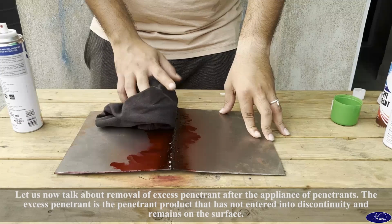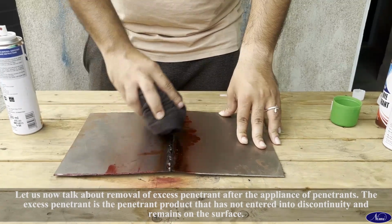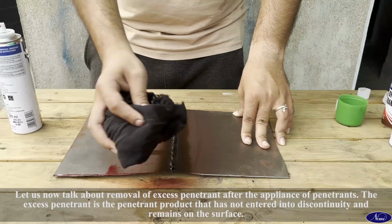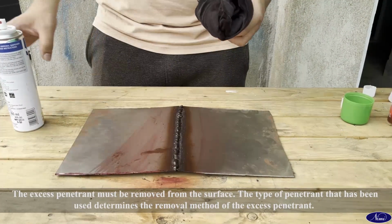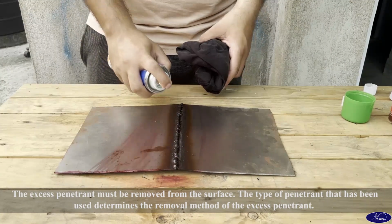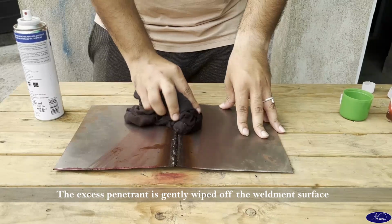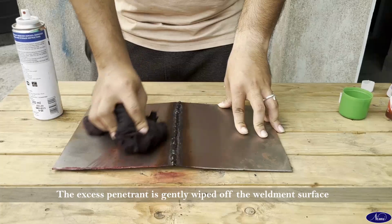Removal of excess penetrant. Let us now talk about removal of excess penetrant after the application of penetrants. The excess penetrant is the penetrant product that has not entered into discontinuity and remains on the surface. The excess penetrant must be removed from the surface. The type of penetrant that has been used determines the removal method of the excess penetrant. The excess penetrant is gently wiped off the weldment surface.